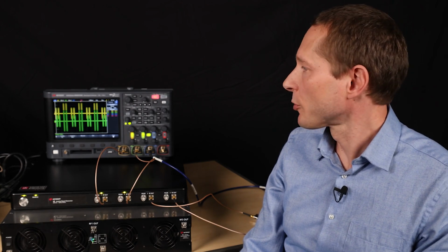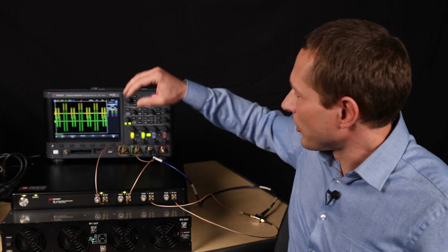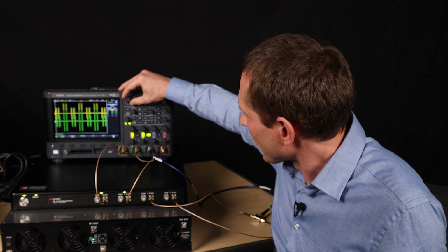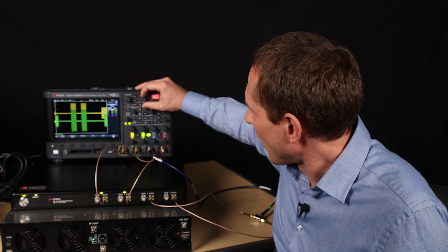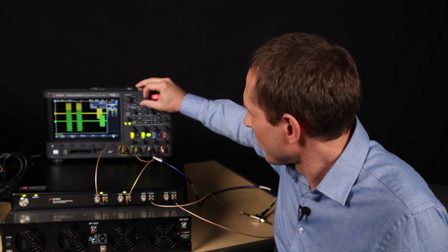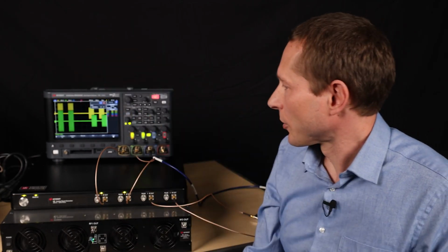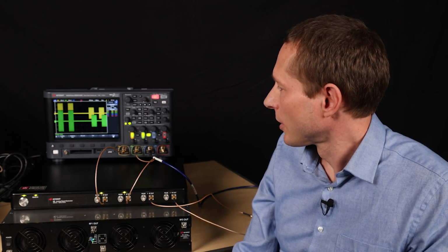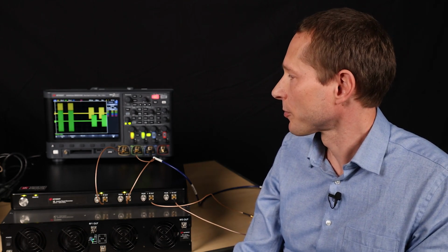We can now verify the timing of our pulse pair that uses a delay offset between the channels by zooming into the traces captured on the oscilloscope. I reduce our time base and shift the capture such that we see one aligned pulse pair and one offset pulse pair. We can now see that we get the precise pre-programmed 200 microseconds offset between the 2 channels.